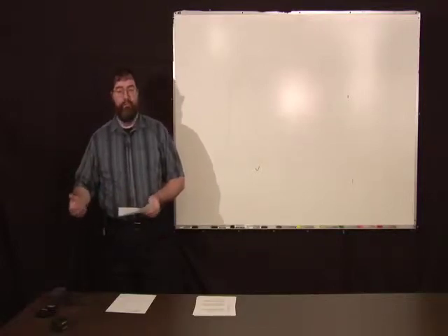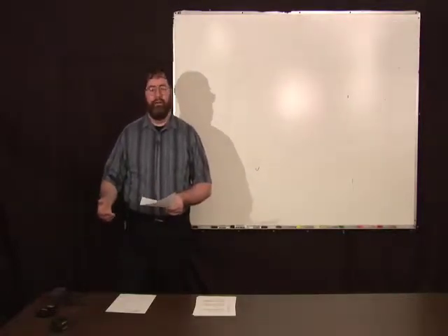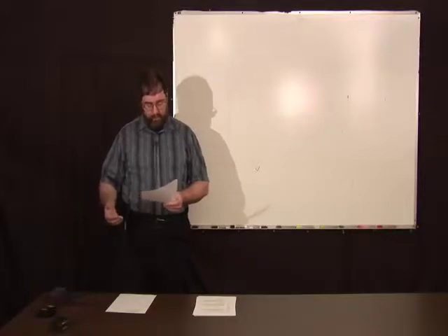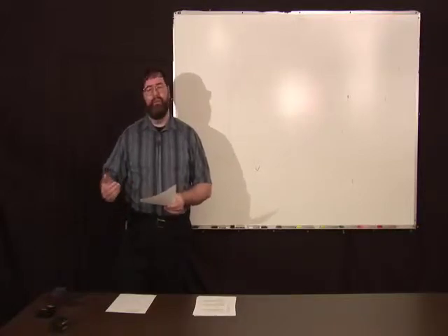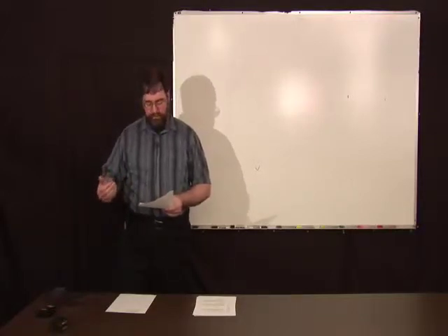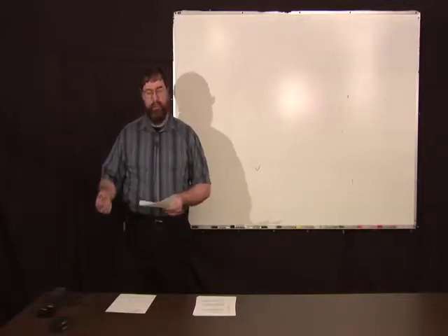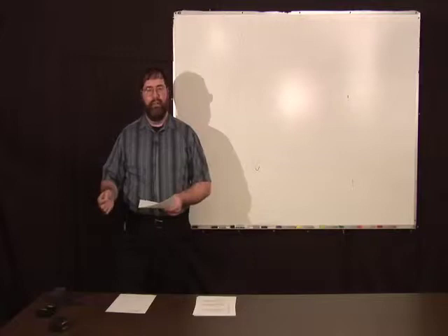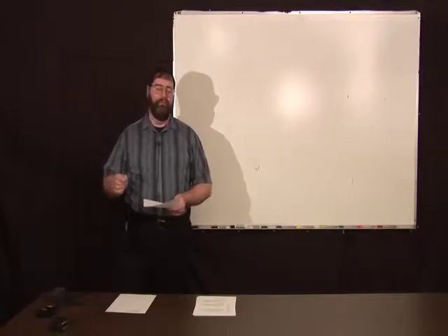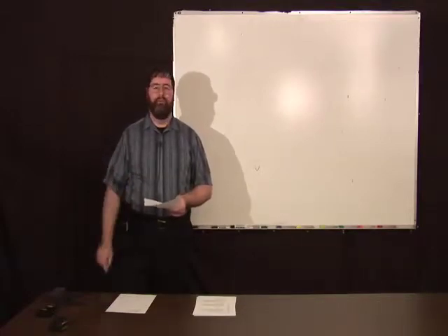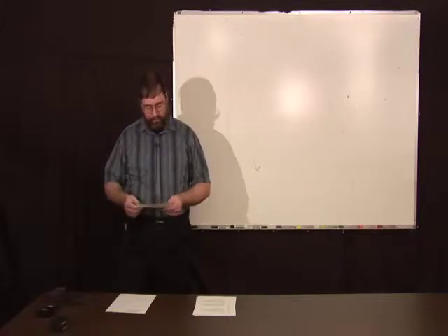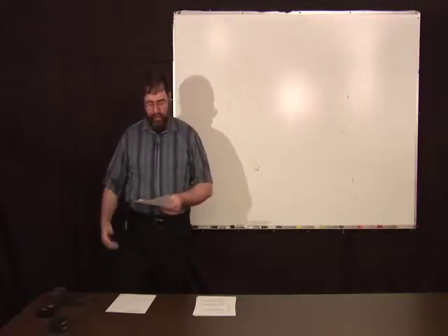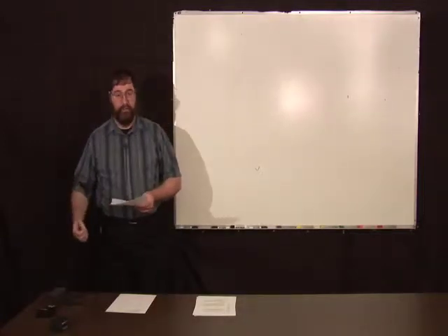The parameter that is being measured has to be clearly defined, for one. You have to have a complete description of the measurement system or standard used to make the measurement. If you don't have that, you can't really say the measurement's traceable, because you don't really know how the intercomparison was made and whether it was adequate or not. Of course, you have to have the measurement result and documented uncertainty for the result.